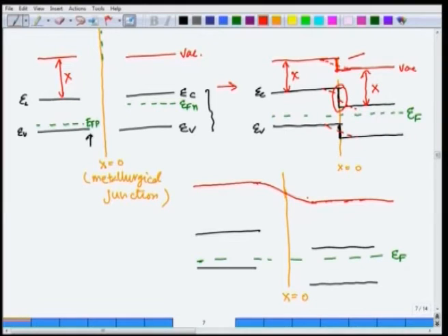Later, in future lectures, you will quantitatively derive this portion of the curve also. And now similarly, because the electron affinity is a material property, with the same values and same slopes I should be able to join these, so that everywhere this remains the electron affinity, and this remains the vacuum level. And now I have got my band diagram, EC, and here is EV, and the Fermi energy is common.